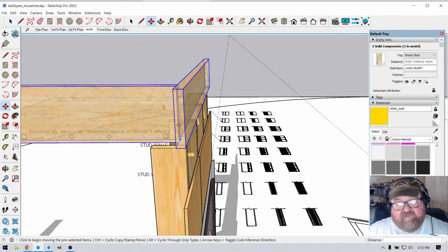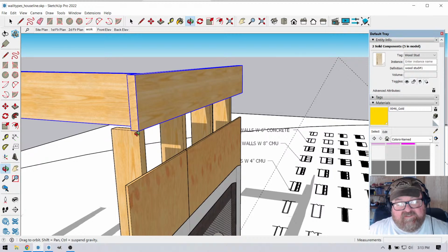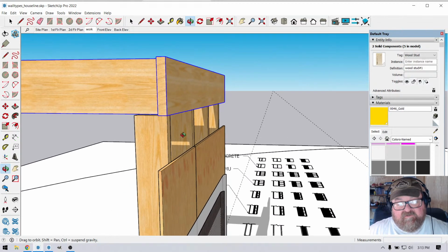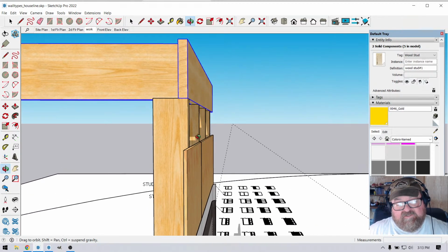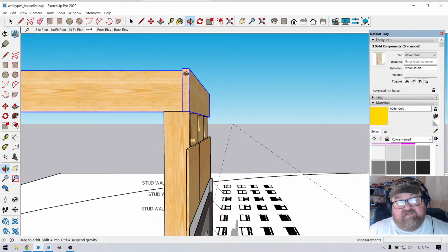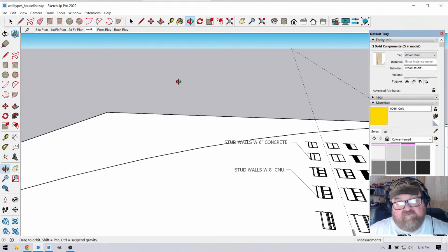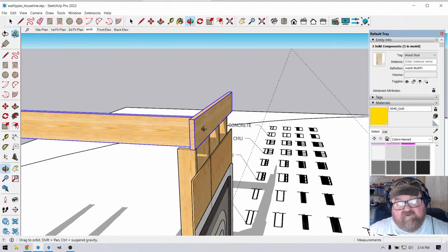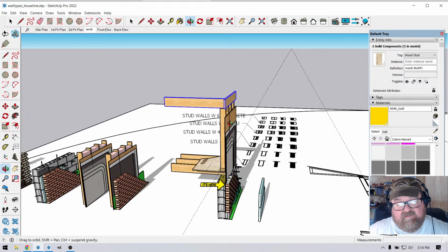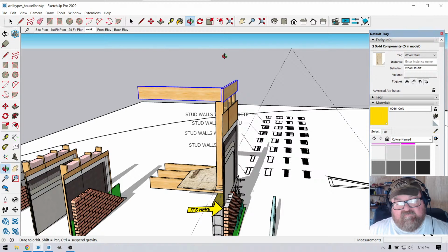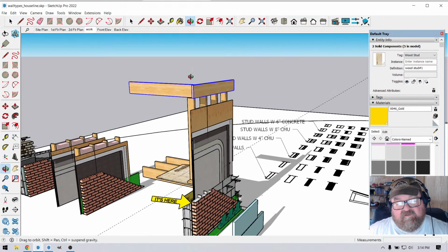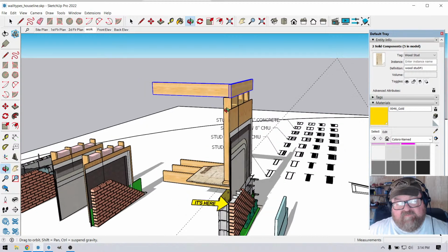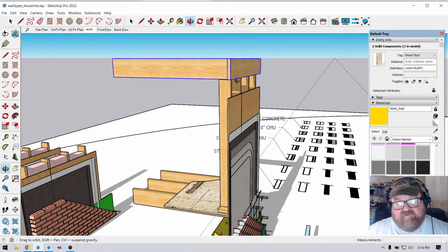Well, there's a top plate. I'm missing that, this is not the top of the wall, I'm just trying to demonstrate. So now the sheeting can start to bypass. But when you start your second floor wall up here, the sheeting is nailed again to this bottom plate, and then you fill in the band with scrap pieces, because again, the sheeting serves the function. Now, I'll be honest with you, a lot of building inspectors overlook that.